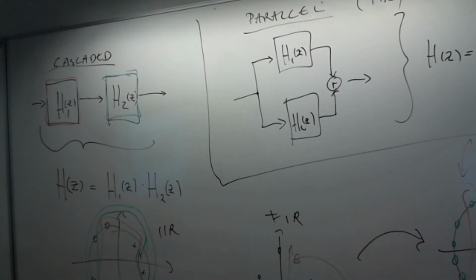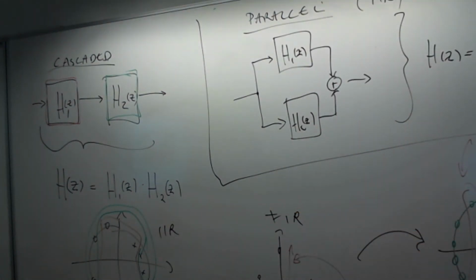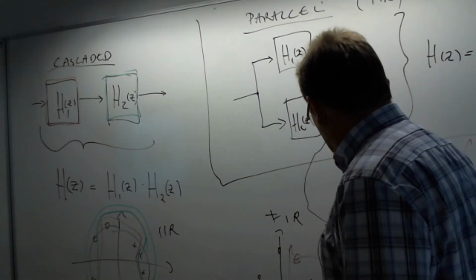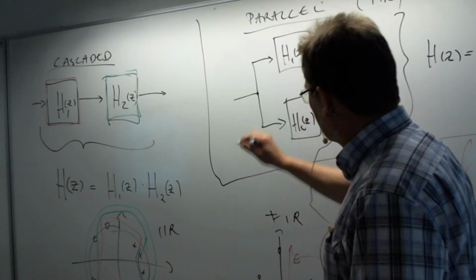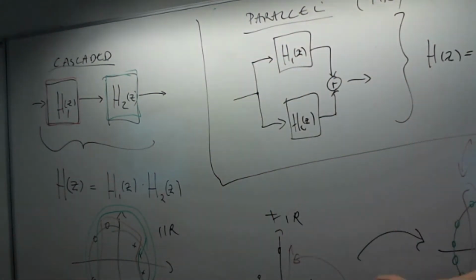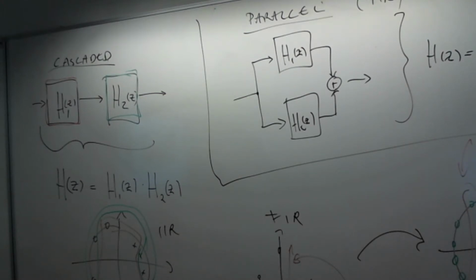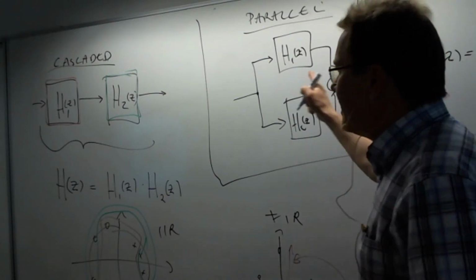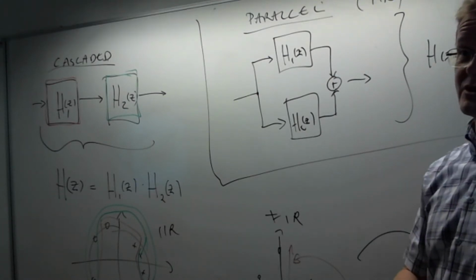Well, a little bit, yes, it would help a little bit on the calculations. You just have to rescale the filters, so basically take a couple of each of those, add some elements and do the final calculations at the end. But it doesn't affect FIR calculations that much. On IIR, this adds a lot of good things, although it's heavier to calculate.